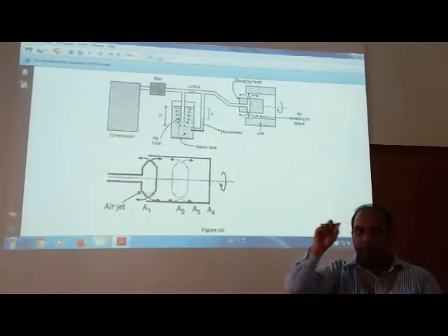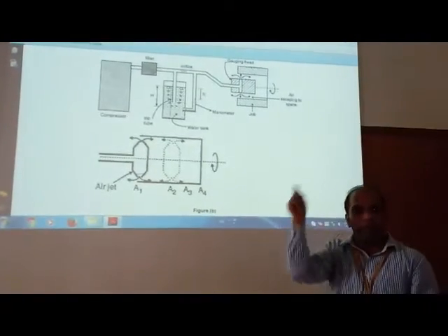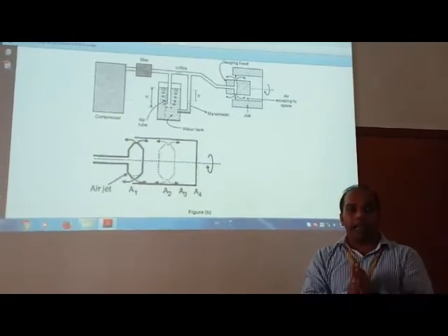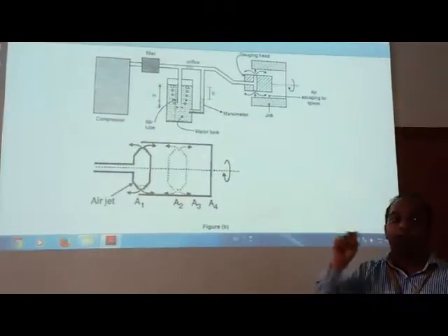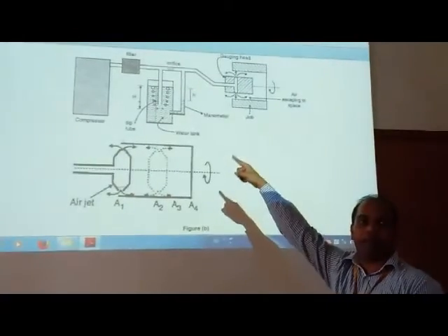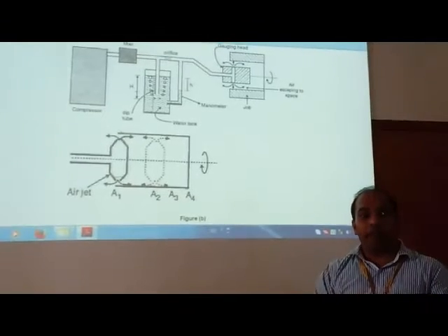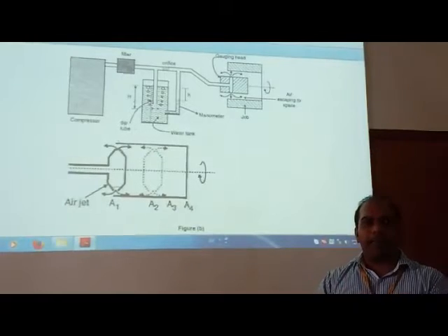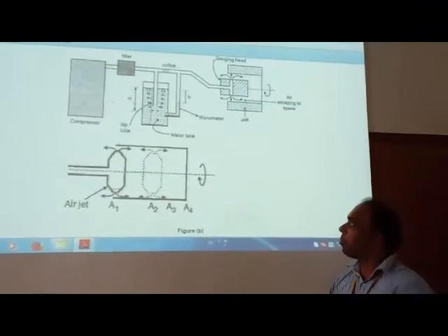If there is any bump caused by a casting defect or forging defect, or any bubbles, shrinkage, gap or crack, these are all defects which will give an extra passage for air to flow. If extra air flows, then the manometer will give us the reading over a large scale. So by noting where extra air has passed or where less air has been received, we can judge where there is an actual defect.